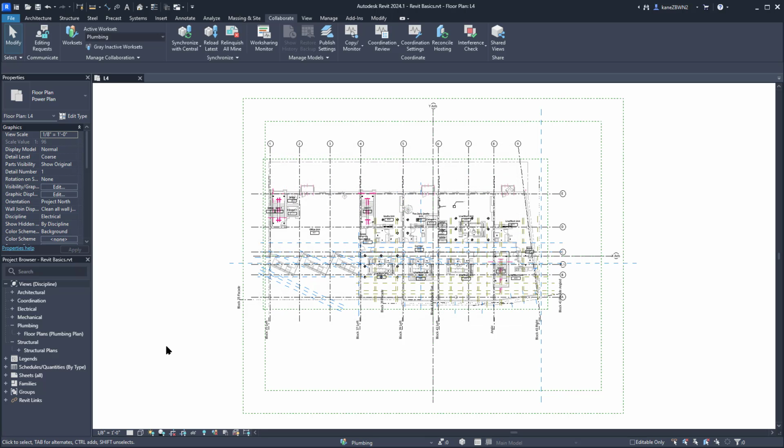Now that we have our worksets defined, we can decide what elements of the model belong in which workset. Something to note, each element of a workshared model must belong to one and exactly one workset. You can't have elements that aren't in a workset or in multiple worksets.